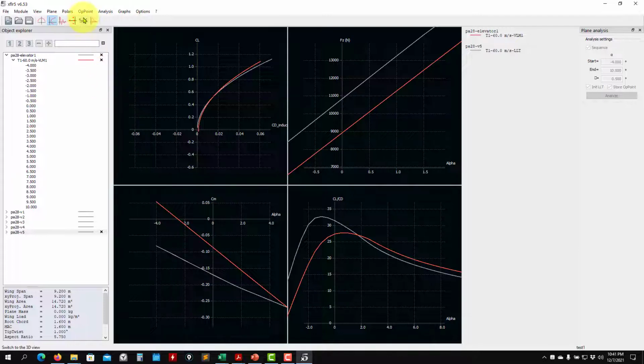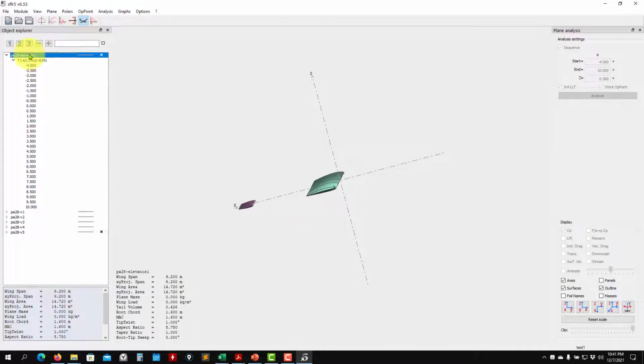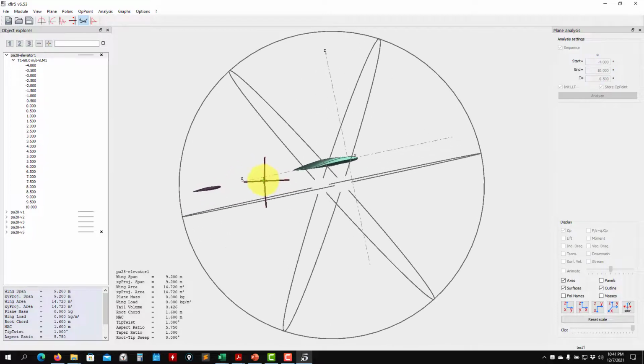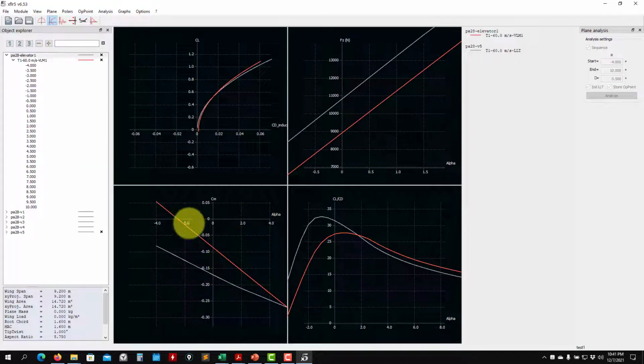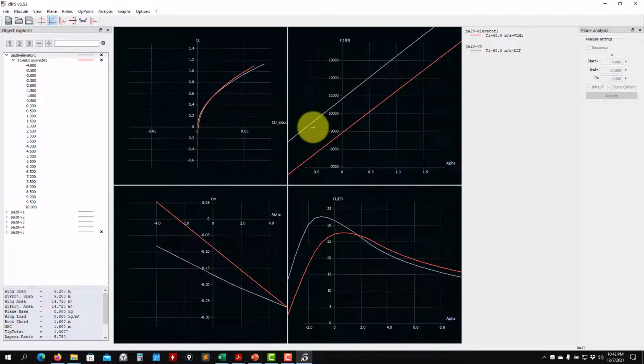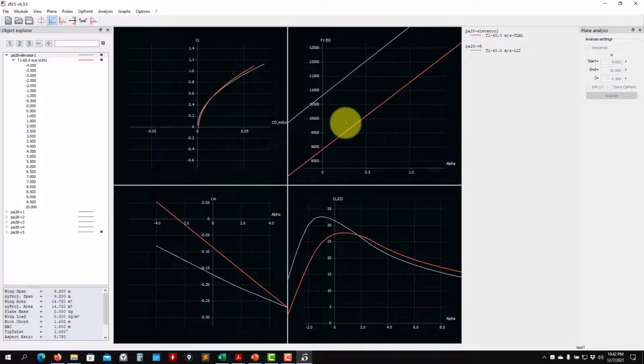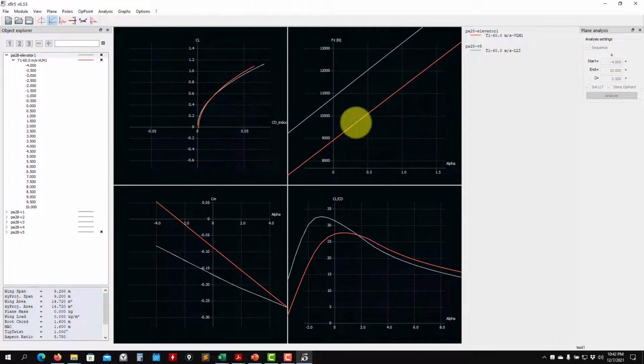What we need to do is look at your airplane and change the incidence angle of the tail. Changing this incidence angle will push down and give more stability. Basically we'll shift this curve to the right until we reach the trim condition. But see that by adding this downforce to balance the aircraft, we're also losing some lift. Actually, in our case it should be about 1 degree that we want for that trim condition. So you see the effect of adding that secondary lift in the tail. That's why it's very important.